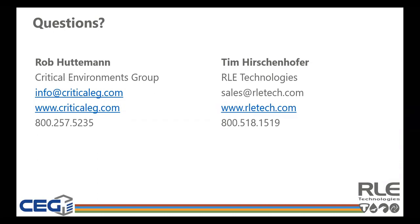Do you guys have a view on air handler fans under the floor versus above the floor? I'm not sure I fully understand the question, but if we're talking about a perimeter room air conditioner and how its fans are set up, usually with a pressurized raised floor, the EC plug fans are the most energy efficient and are typically included with a manufacturer's unit.